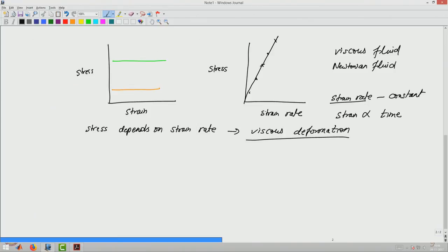However, there is a distinction in terms of what the basic mechanism is and how it is related to strain rate. Therefore, in general, when we look at the class of materials which are yield stress materials, we could have their response being described as elastoplastic, viscoelastic or elasto-viscoplastic. These are the phrases that you will hear people use when we describe the overall response. So, elastoplastic implies this is before yield and this is after yield.